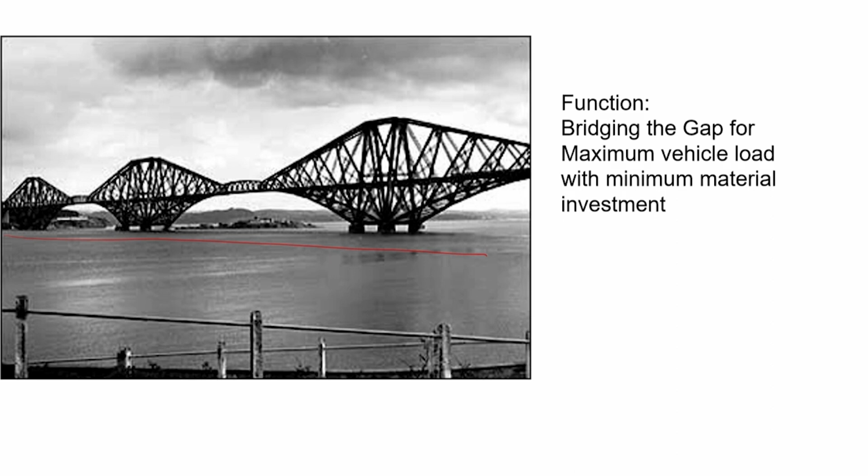So this design, once upon a time it was made possibly by using cast iron, was an economic design. But then structural steel was developed, and with that the manufacturing process also became available, so that you can give much more. We have seen in our last lecture about the shape factor that structural steel has a much higher shape factor. So today this type of design is not required, because you take advantage of the shape factor and go for other types of bridges, like a suspension bridge or things like that.